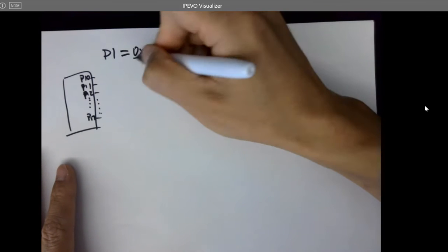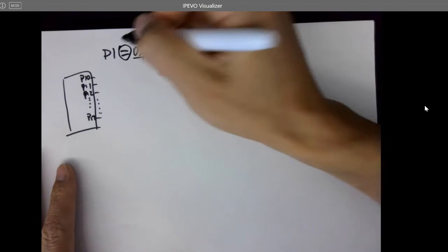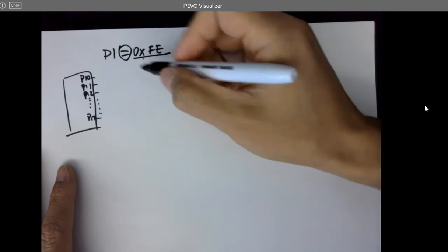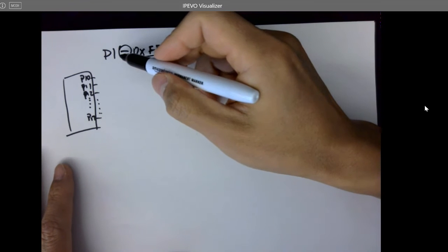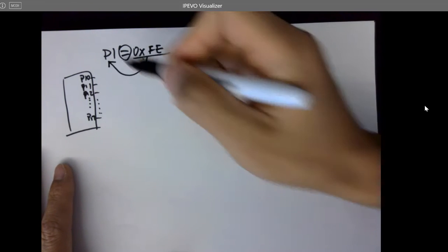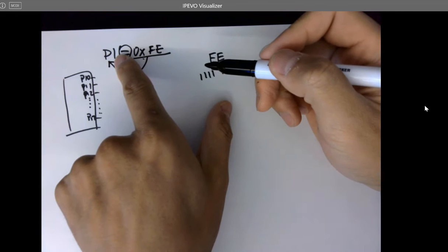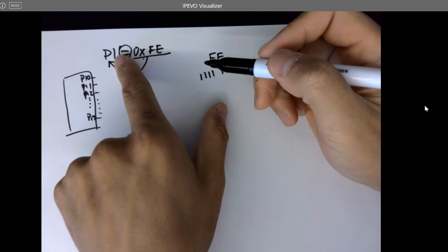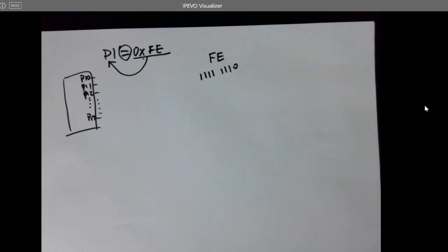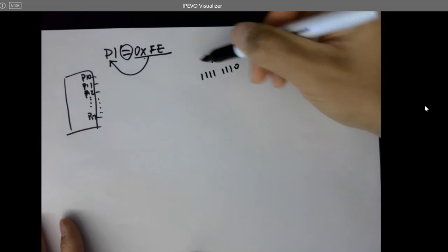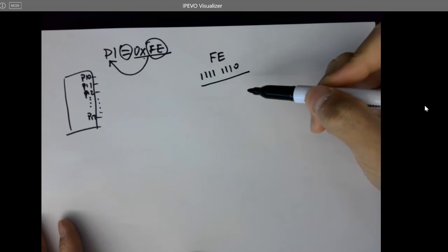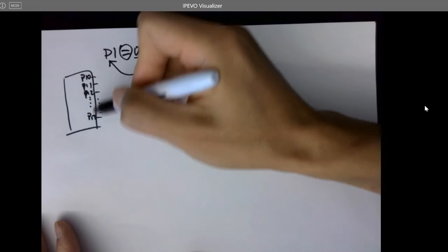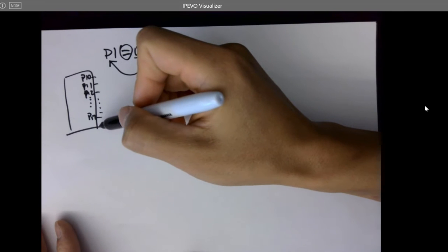And if you're assigning, this is an assignment operator. So when you're coding, this is not the equal sign, it's an assignment operator. So it's assigning this number to P1. P1 is a register. It has 8 bits, like a memory bank of 8 bits. So whenever you're assigning this hex number to it, you're assigning 8 binary bits to these pins. They are physical pins on the chip.